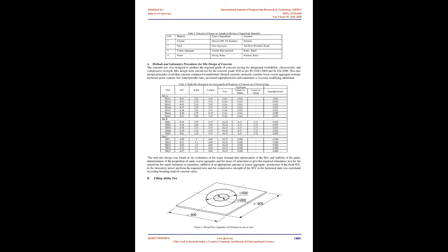It is estimated that about 70 million tons of RHA is produced annually worldwide. Rice husk ash is a pozzolanic material having physical and chemical properties, and this study was limited to assessing those properties. This RHA is a great environmental threat, causing damage to the land and the surrounding area in which it is dumped. The rice husk itself has a very rough surface which is abrasive in nature.